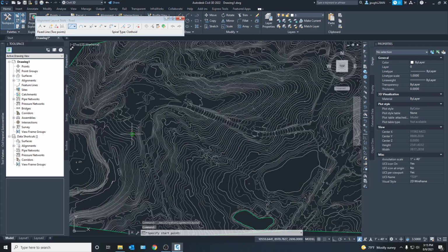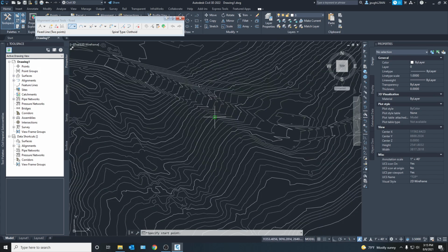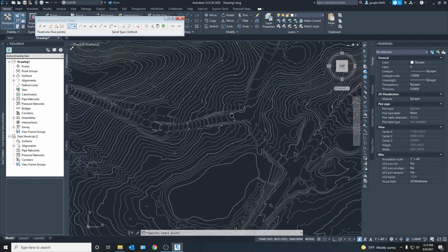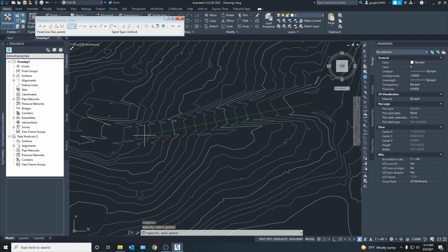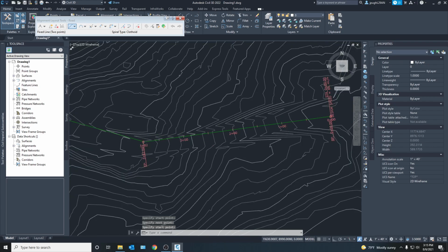So we've got a two-way line. And we're just going to come through here. You can see this is an existing grade surface that already has roads on it. So we're just going to go on a road and start making the alignment. We're going to go this way, and we'll just kind of follow it. It doesn't really matter too much for this kind of video. Press enter, and there you go. We've got stationing,